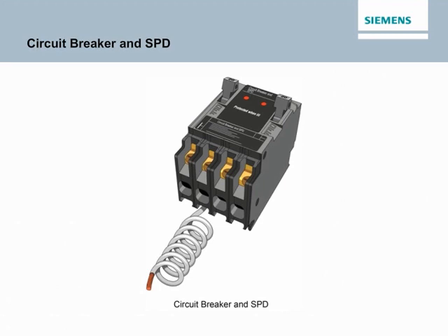The circuit breaker in SPD notifies the owner of loss of surge protection by tripping one or both of the circuit breakers. The value of this feature is enhanced by using one of these breakers for circuit protection of frequently used household circuits, so that the circuits controlled by the breaker also indicate the status of the surge protection. If one or both of the circuit breakers have tripped, turn both circuit breakers to the off, then on position. If either light is not illuminated, the device may still be used for circuit protection, but surge protection is no longer provided and the device should be replaced by a qualified electrician.